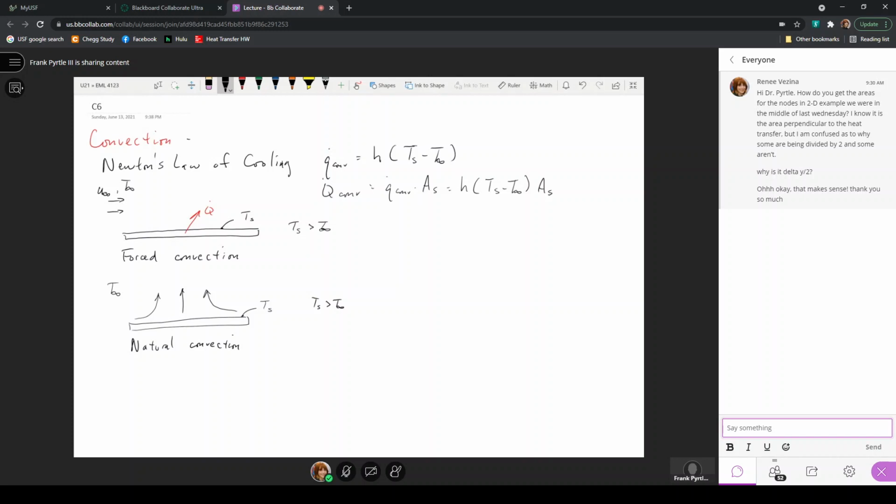So here, the difference between forced and natural convection is that the heat transfer coefficients associated with natural convection are just much lower, because here we're depending on the differences in the specific volumes of the adjoining molecules, rather than using a fan or some other means to actually move the fluid over that surface. Those are the types of convection, when we're considering no phase change, that are often considered. But there are lots of other considerations that we have to make when we are making convection calculations.